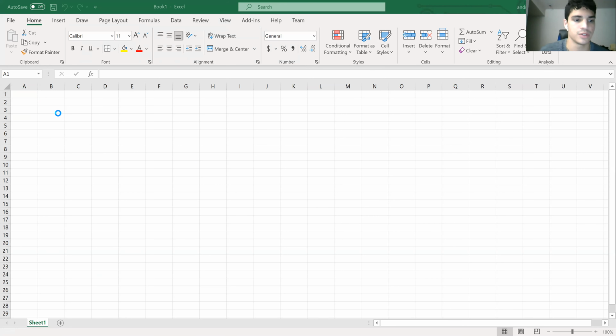And now we're going to graph our alphas and CLs. The first thing we could do is just click these two, insert, make a scatter plot. Basically, we could label it as the CL versus alpha. And then we can do the same for the rest of these. So you can just hit insert, scatter plot, left click